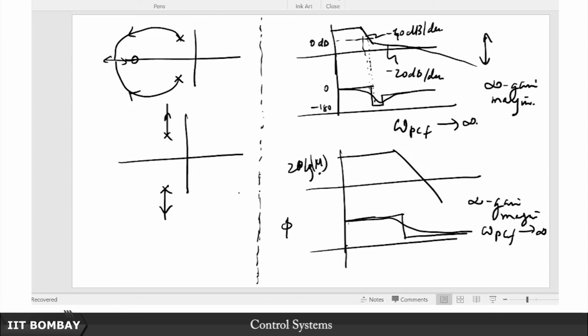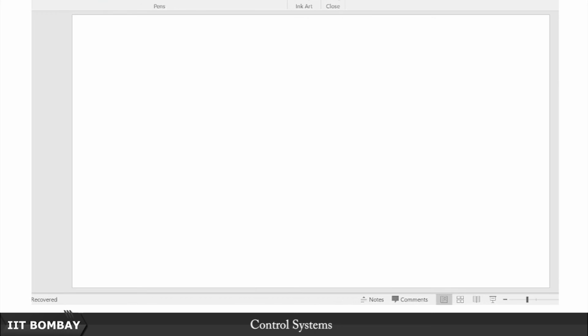Okay. It is only the Bode plot which will give you information about both of these simultaneously. So, in some sense it gives you something more, it conveys some more information, and that is why we are fond of Bode plots. But, and here is where I will leave you with a little bit of discomfort about Bode plots. You see, this is all very well and good when you have nice systems, but let us not forget about the pathological case I had drawn a while back.